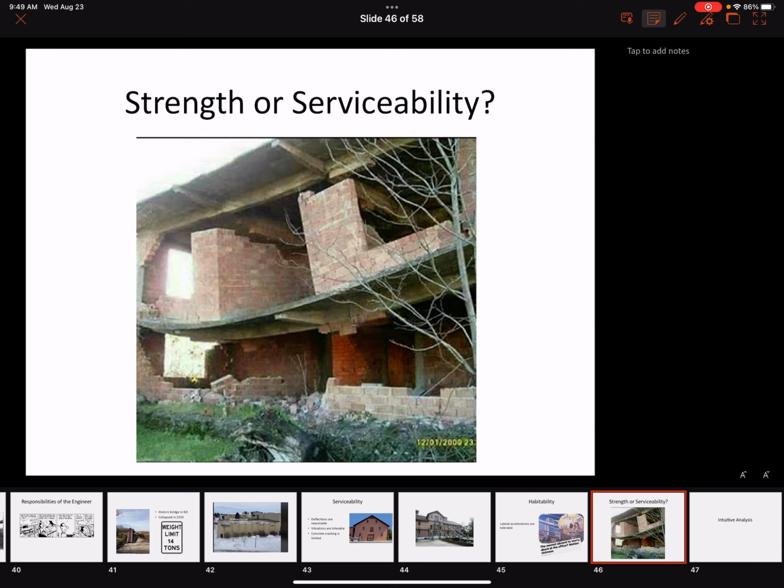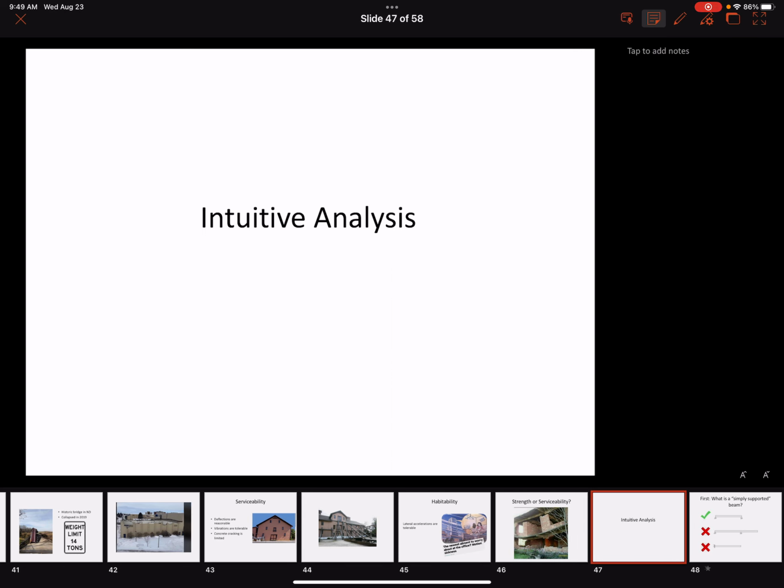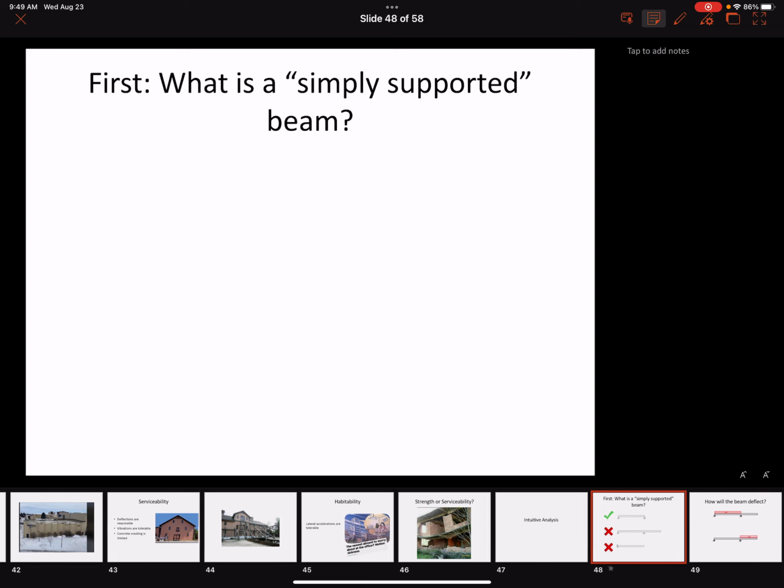So you could argue that the floor itself hasn't failed. It depends on what criteria you're considering. Has it yielded? Maybe. If it's yielded, then it's probably failed. But you could argue that it's still meeting its strength demands. But I wouldn't want to test it out by putting any more load on it. So definitely not safe.